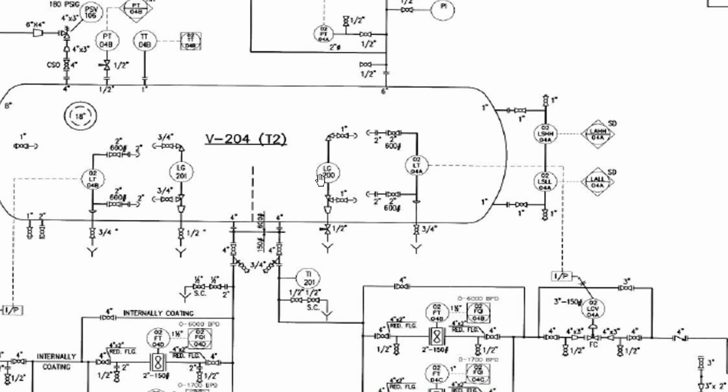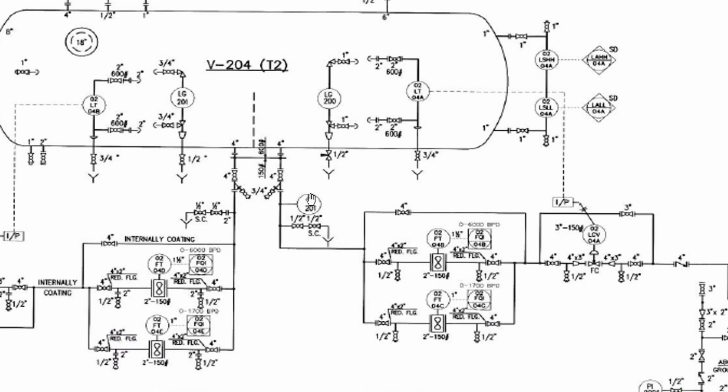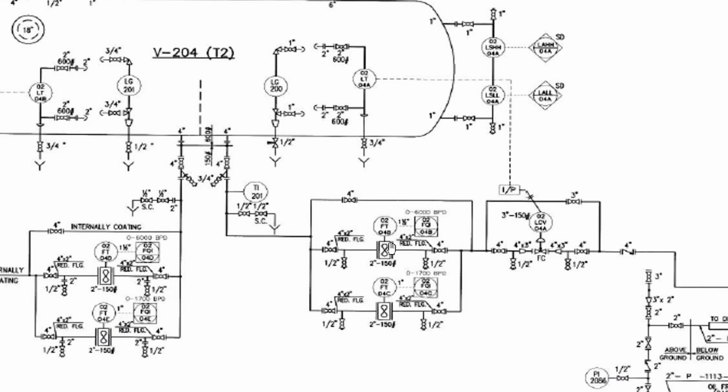Coming to the oil side, you can see the level gauge. There is another control system there that I will discuss in another session. Now I am focusing only on field instruments: only one circle with a notation inside. That is a field instrument, the level gauge. In the oil outlet there is also a temperature indicator. The meaning of the notation I will explain later. The field transmitters we can discuss in another area; they are not part of this one, so no need to discuss that.